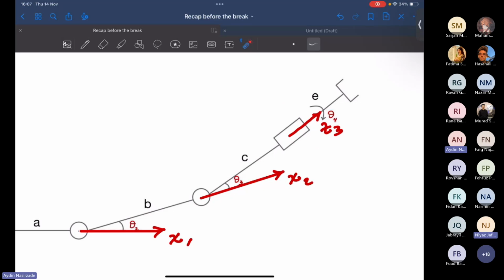So we should remove the origin O3. Absolutely, so we have to move the third frame so that X3 can intersect the extension of Z2. And I think this is good. I'm choosing this Z3 this way, and perpendicular to Z3, I have X3. I guess, yes, this way. This is my X3.